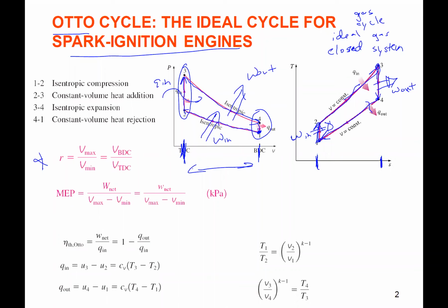Okay. Mean effective pressure more just kind of normalizes the work. So this work net is what you have in this area right here, right? This mean effective pressure says, okay, what if we just changed the displacement from here to here? But what mean effective pressure would it be right here if we just had that displacement volume and had that same area of work net? What would that pressure be? And that normalizes whether you have a small engine or a big engine, because if you just increase displacement volume, all it does is make this area bigger here, and so forth.